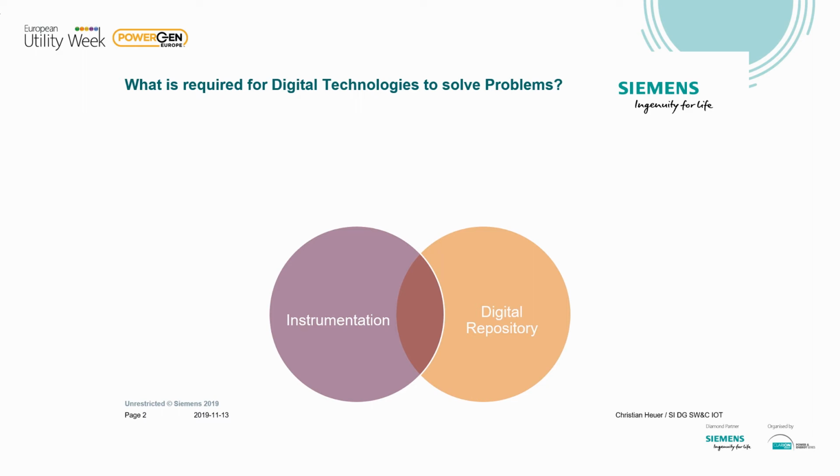And now the third thing that's really interesting is how do we represent the system itself in the digital space? What does it mean if a power quality sensor is measuring something somewhere, and what does it mean to the system? And what is happening if it stays like that? So example, we see an overload. We see, for example, a transformer, we are measuring the temperature, and the temperature is going beyond a certain threshold. Then in the end, we need some kind of domain intelligence to put some context to it. So is this a good thing? Is it a bad thing? Do we want the oil to be hot? Do we want the oil to be cool?